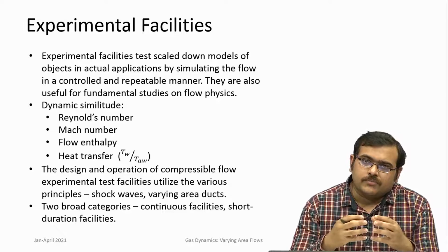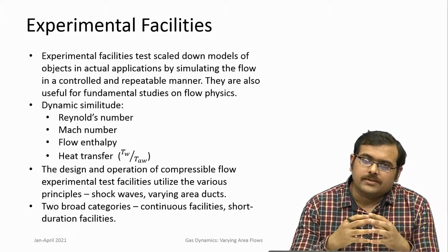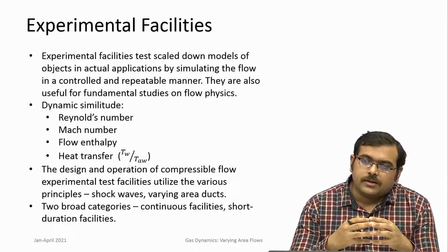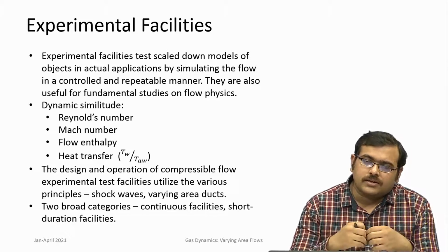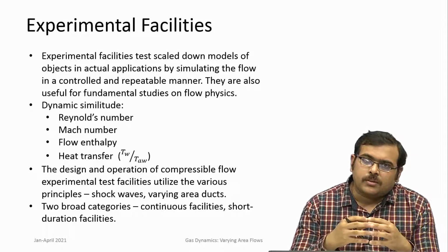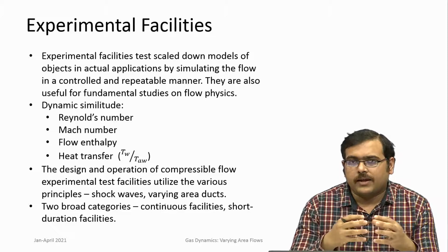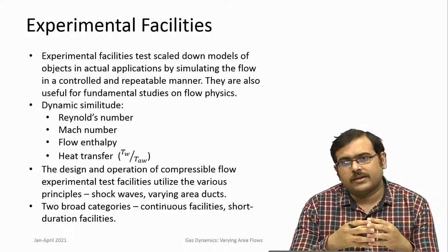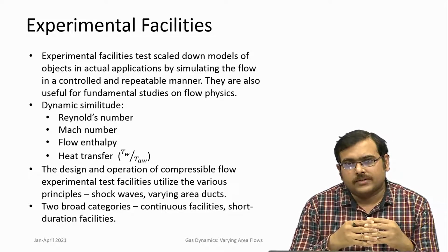By scaling the model, you have maintained the geometry in a scaled fashion, but that is not sufficient. You should ensure that the forces are also scaled in a commensurate way, and this is done by a Buckingham pi analysis that would have been covered in fluid dynamics classes.